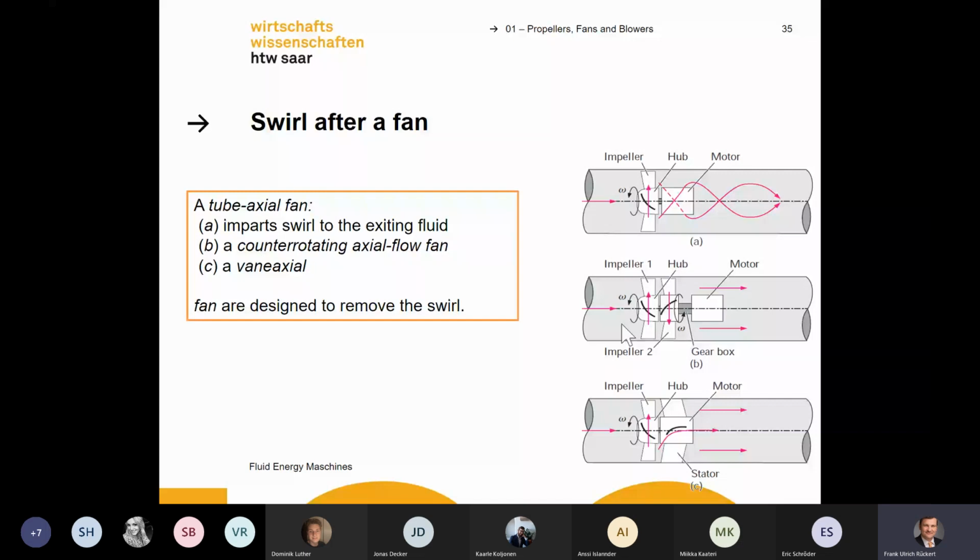And also gears, I explained to you about mechanical losses. If we have a lot of gears and a lot of belts, they will also always cause friction and losses. So it's better to use the engine directly. That's more efficient. And of course, we want to cool down the engine.